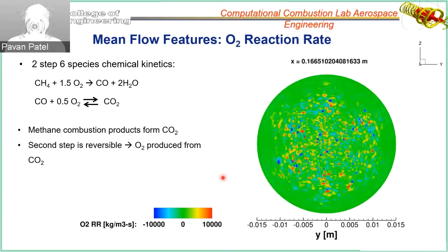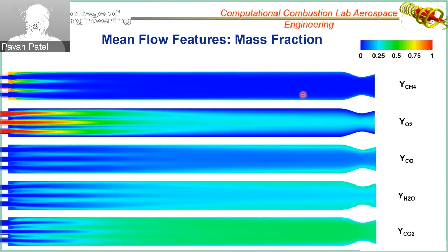And so if we look at the overall mass fractions of the major species involved, which is the fuel here, the CH4, the oxygen, carbon monoxide, H2O, and CO2, we can see that in the fuel, there is some unburned fuel at the walls of this chamber, and it may not be very clear here, but there is some fuel exiting the rocket engine, which is not really very good, because CH4 absorbs a lot of heat, and that's not really good for the environment. Similarly, with the carbon monoxide, you can see unburnt carbon monoxide is leaving the chamber and also the engine, which is not really good for the environment. But O2, H2O, and CO2, most of it is in the core, unlike the CH4 and CO. O2 and H2O is fine. CO2 is harmful for the environment, but it is a combustion product. So, ideally you'd want to use up all your fuel and make sure there's also no carbon dioxide.